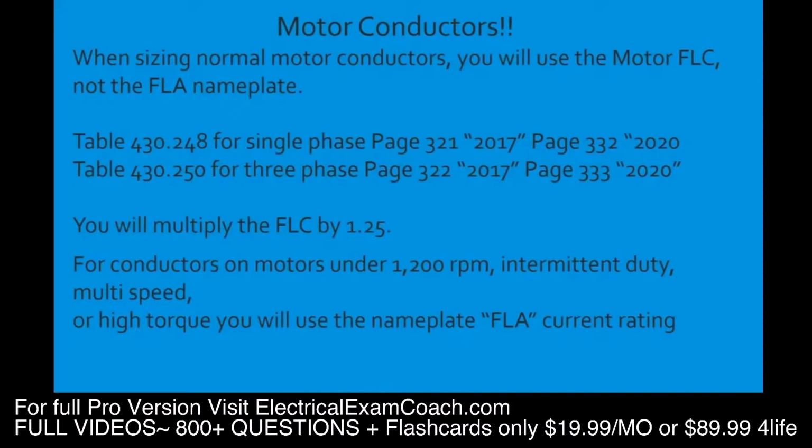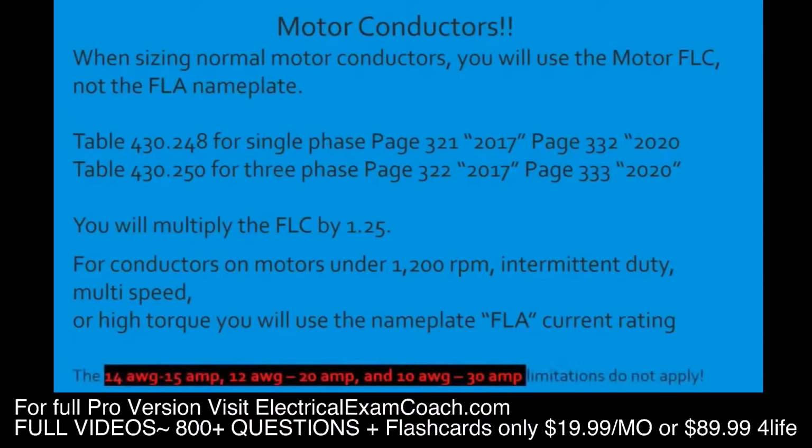Why the code book doesn't stick with FLC or FLA only, I don't know, and I wish they would simplify it. Also, one thing I want to note for motor conductors: remember in the ampacity lesson, we learned that 14 gauge wire can only go on a 15 amp breaker, 12 gauge wire can only go on a 20 amp breaker, and 10 gauge wire can only go on a 30 amp breaker? Well, with motors, these limitations do not apply. Those rules do not apply. So now that we've set the ground rules, let's get to it.